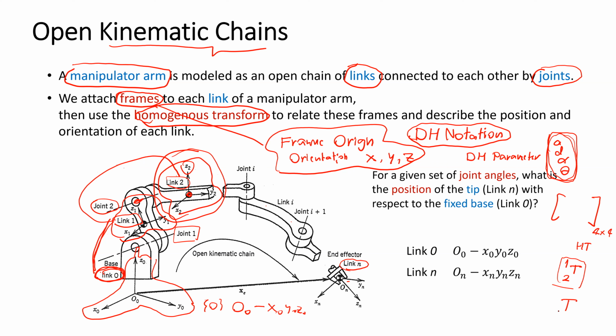And we have the homogeneous transform that relates link number 3 to link number 2, like this. And when we obtain the product of the homogeneous transforms, we can find the forward kinematic. But here, the homogeneous transform will relate the frames. And it can describe the position and the orientation of that frame with respect to the previous frame and also with respect to the base frame.